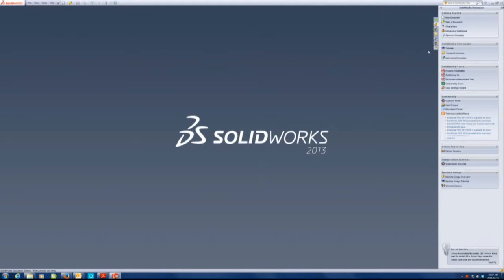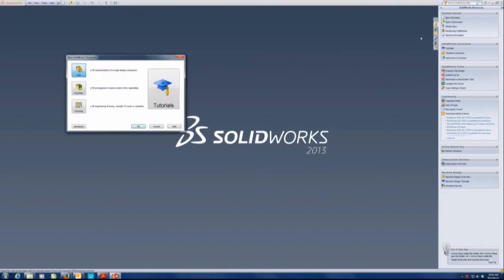So every time we start a new document, we click on New Document. So there it is, or you can click on New Document up at the top here. It's the same thing. You'll notice in SolidWorks there are quite a few functions that double up, so there's more than one button to do the same function. I don't really mind which one you use, as long as you use one of them. You have to get to the answer, so it doesn't really matter which one you use. All right, you click on this one for now. So we say New Document, click on Part, and we say OK.